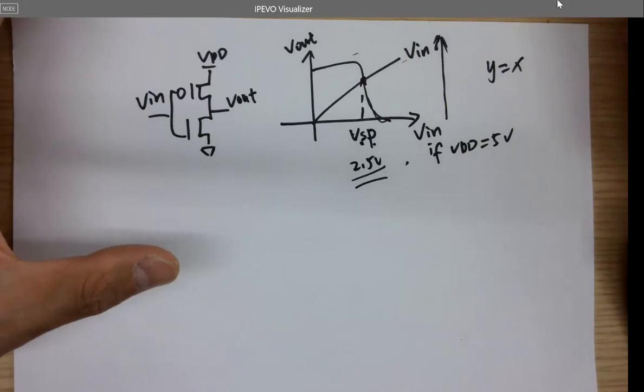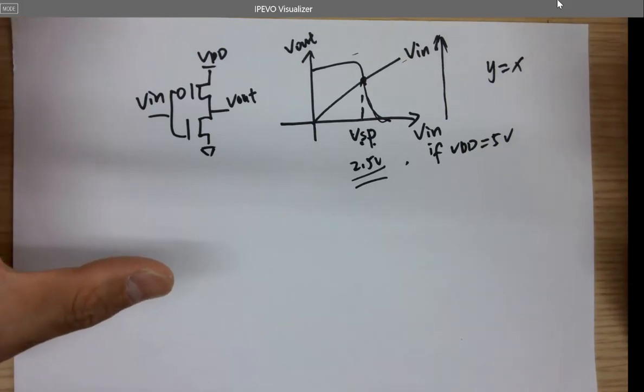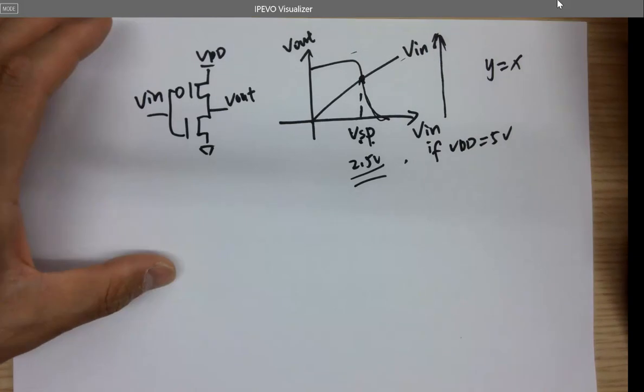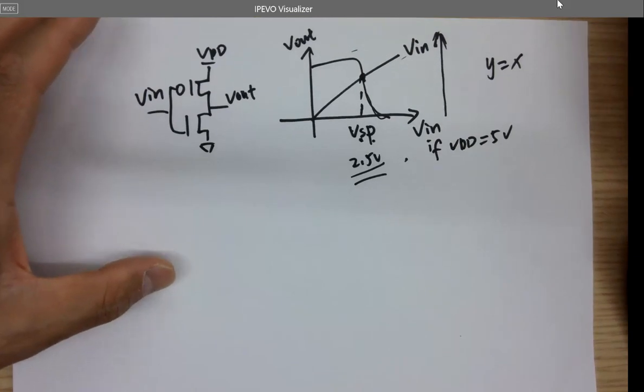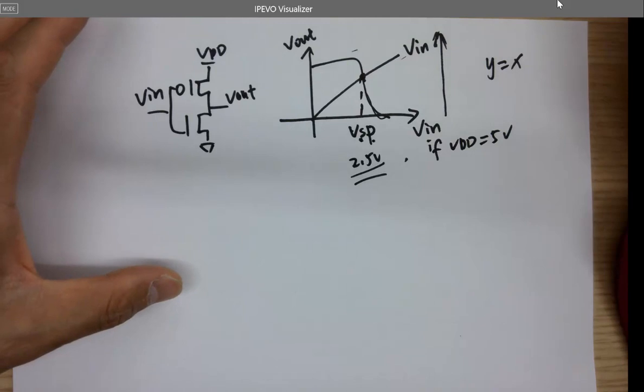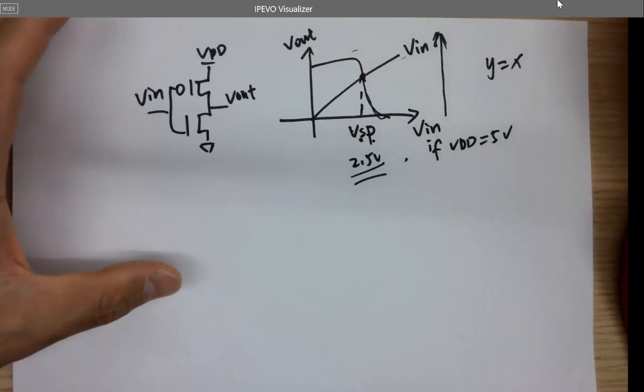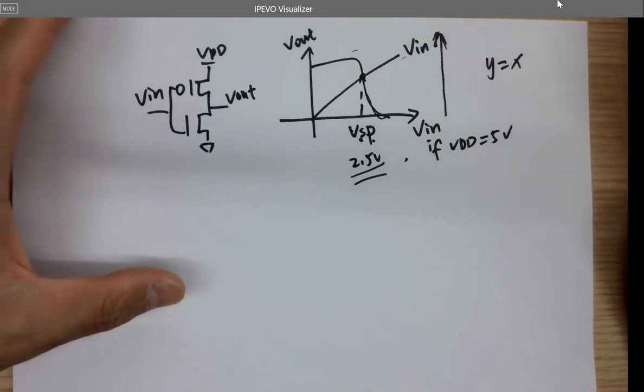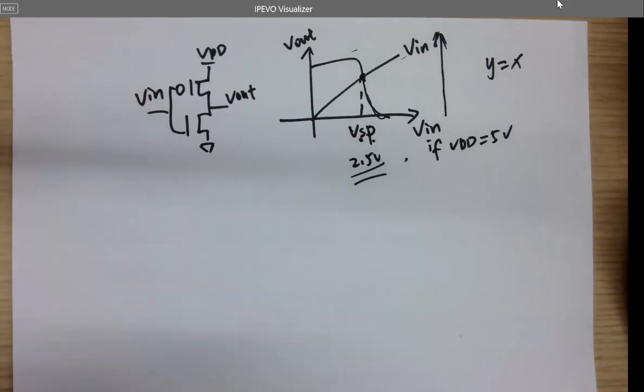So they just use the minimum size for the width and length for all the transistors, pretty much. It's 5 nanometer technology, so all the transistors' lengths are at 5, and they try to use a 5 for their width as well if it's just pure logic, and you don't have to run a lot of current in it. So you don't have to make the transistor very big or very wide.